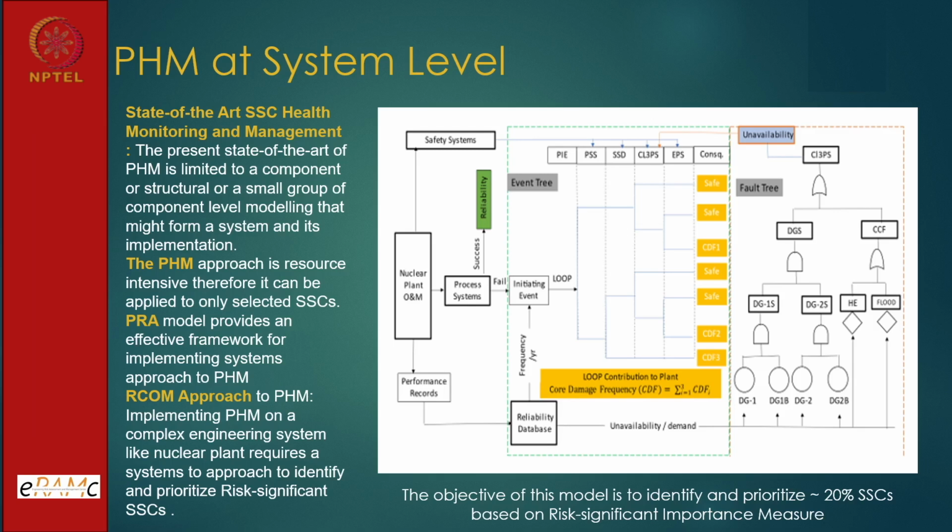So suppose through PSA, fault tree, event tree and all, I produce a list of components with importance measures, as we have already discussed in previous lectures. Then we take the highest-importance 20% of components, and of course with a qualitative evaluation, we can work on those.